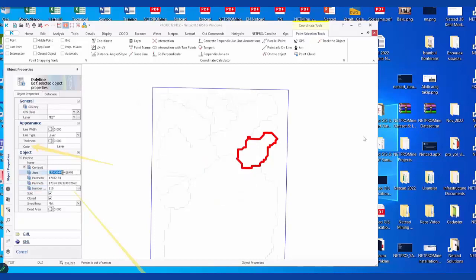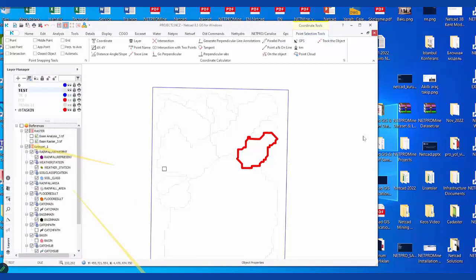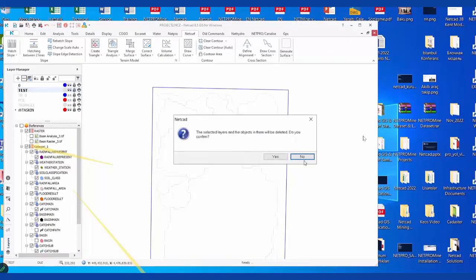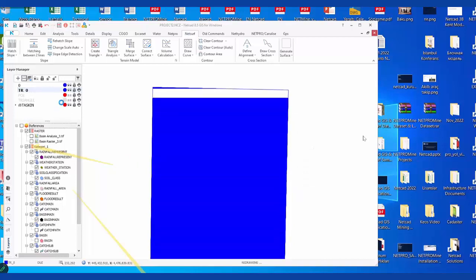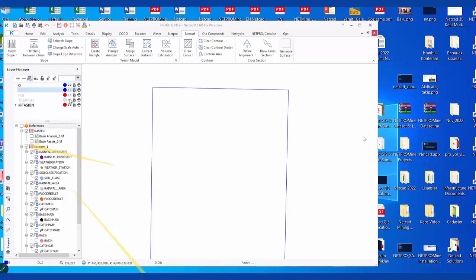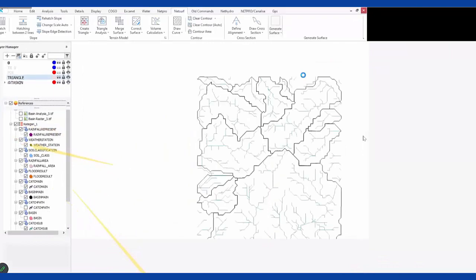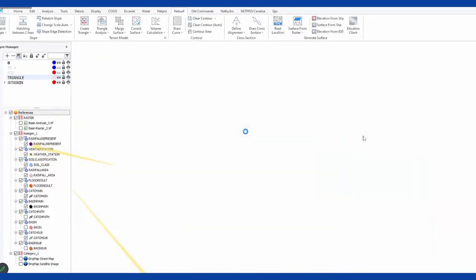the area is, okay, 12 million square meters. So it's going to be 12 square kilometers, which for Snyder is actually fine in that area. It's not that small as it seems. Okay. So according to the Snyder method, I will move forward with my design. I will bring back the references. All right.